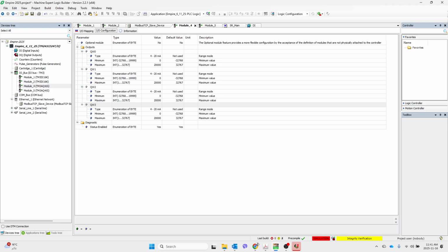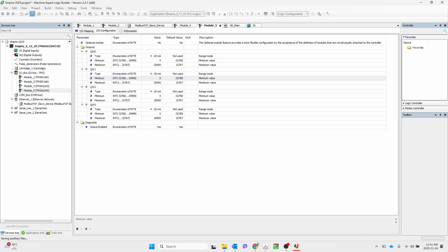I will make a double check at the site regarding the actually measured or injected milliamps on each output before connecting it to the controller, because an incorrect current will harm or, in a severe case, damage the input of the controller. So be assured that you send the correct signal value to the specific output.